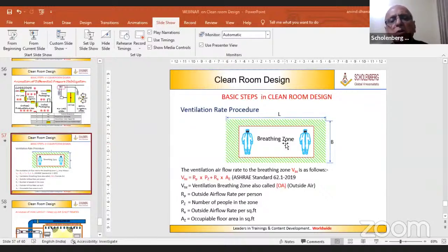But Samir, we have a very good course on heat load estimation, totally animated, beautiful psychrometrics. All the lines are moving automatically, very easy to understand, supported by a totally automatic, formula-linked Excel sheet. So you don't have to worry about the formulas. You don't have to worry about the factors. It's all there. In the heat load, normally we assume factors. The U factor we explain to you how you calculate, because the factor depends on the building material.